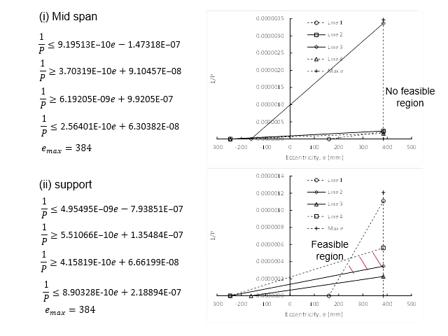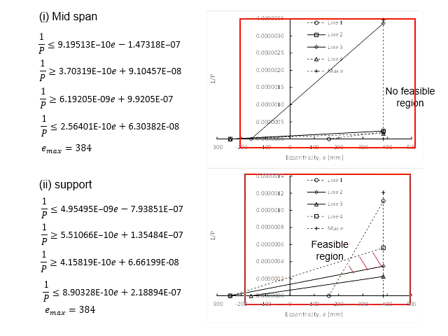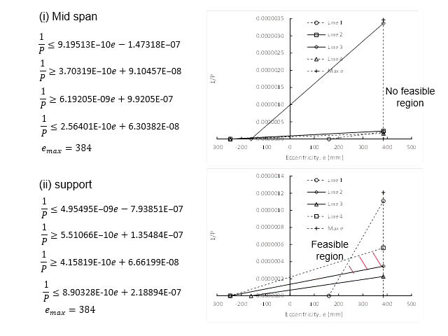As it is mentioned that the precast member here is considered as a pre-tension member, it is easier to be constructed with a constant E throughout the member. Otherwise, you will have to use the deflected tendon methods to adjust the E. This is also possible, but the only requirement will be you must find a feasible regions at the midspan and also the feasible regions for the support. Propose appropriate P and E, which is workable so that the sections will be safe.